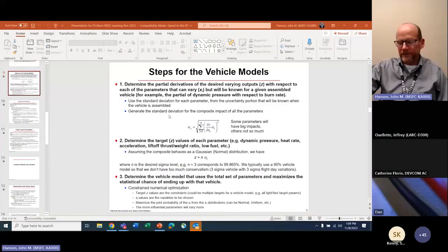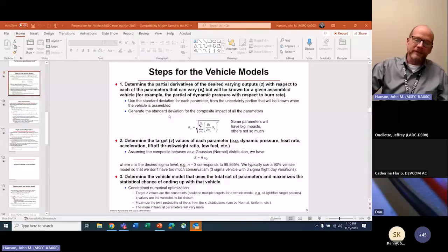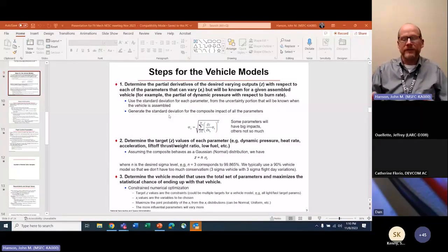So I'll know for this rocket, here's what the test stand measurements say for those engines that are on that particular rocket, because I want to make sure the engines are going to work. So I fire them up, then I go put them on the rocket, and I know their parameters better. And the ones I measure for a different case of launching this rocket will be different. So there's not as much uncertainty as there was early in the program, but there still is some uncertainty on vehicle to vehicle variations, even after I've started manufacturing these things and I have a lot better handle on them.